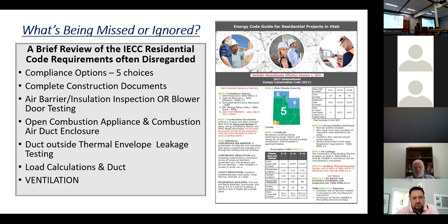My son used to live in St. George. And if you were sitting in the family room under the heat register, the supply air, and the system had been off for a few minutes and it turned on, guess what the temperature of the air coming out was? Well above 100. It didn't make it up to 140 in a 20-minute off cycle, but it was really hot. And you have to purge it all out. So where do you blow the hot air? In the house, and then you remove the heat with the air conditioner.